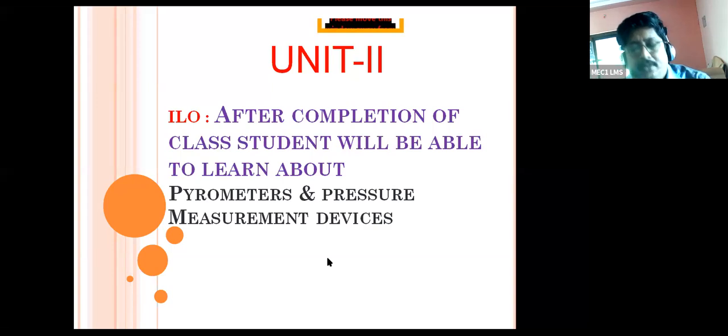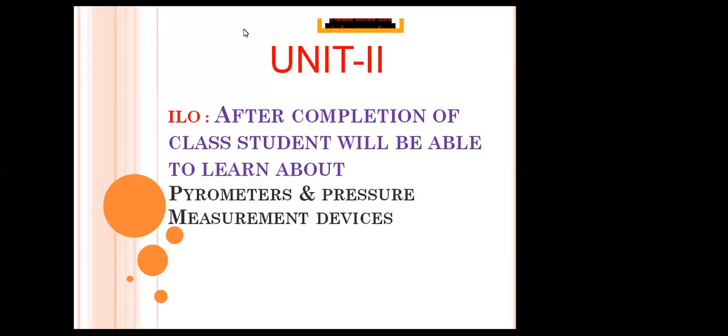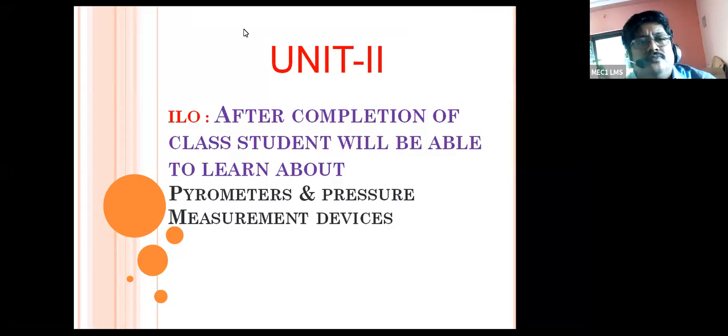In the thermistor, there is a positive temperature coefficient and a negative temperature coefficient. The range is minus 250 degrees centigrade to 500 degrees centigrade, and with the help of the thermistor you can measure temperatures. In the negative temperature coefficient, the resistance decreases with the increase of temperature. Whereas in the positive case, the increase of temperature is proportional to the increase in resistance.